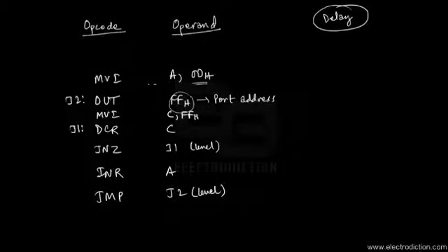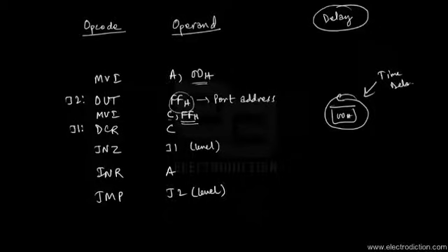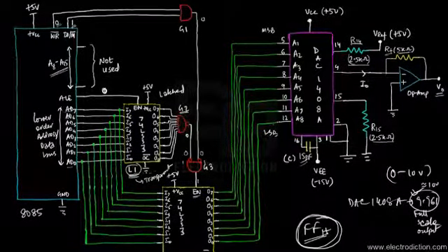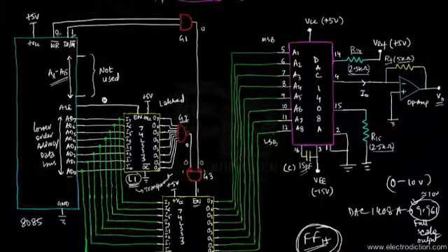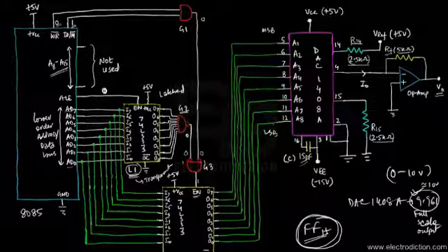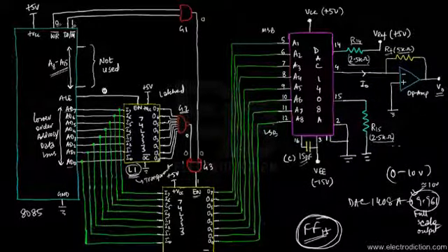Now I'm going to explain what happens in this program. Every time the register A is incremented once, we just start a counting process, where we load the register C with the data FFH and then go on decrementing it until the register C contains 00H. So this just introduces a time delay. By doing this, we're making the 8085 take a little longer to execute the entire program. It's because the conversion time of the DAC chip is more than the time in which the 8085 would execute the entire program. So we need to give a delay in order to synchronize both the devices.